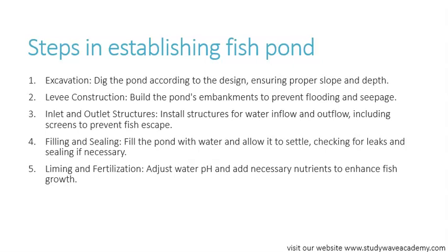Make walls around the hole to keep water in. Do we understand? Inlet and outlet structures. Install structures for water inflow and outflow, including screens to prevent fish escape. Put pipes or channels for water to come in and go out.